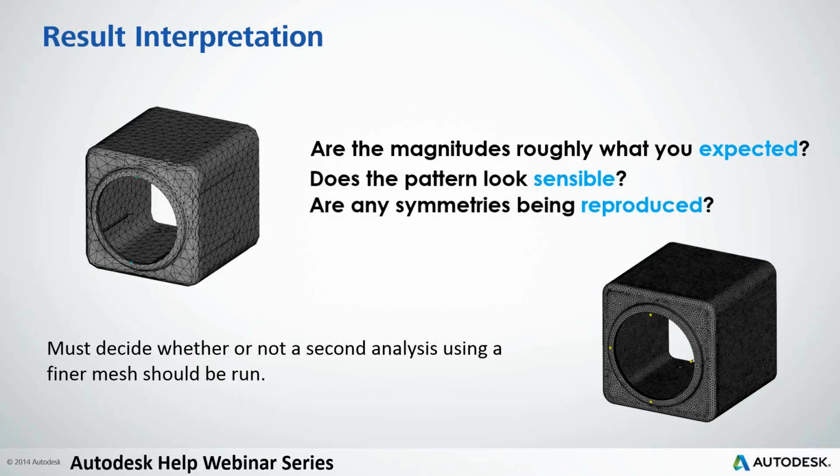So you can see on the left there's a much coarser mesh than on the right, bottom right there, and that could potentially cause some trouble for being able to see exactly what's happening with regards to why a part might be deflecting a certain way. So adding some refinement, maybe not as much as I did in this screenshot here, but it could help to make things a little bit clearer for you.